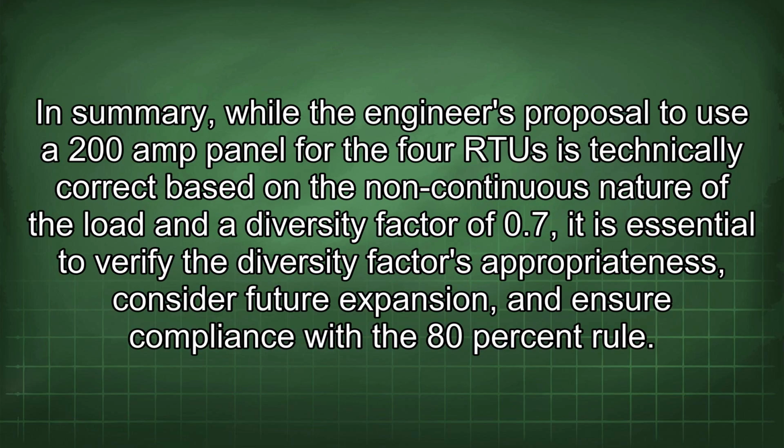In summary, while the engineer's proposal to use a 200-amp panel for the 4 RTU is technically correct based on the non-continuous nature of the load and a diversity factor of 0.7, it is essential to verify the diversity factor's appropriateness, consider future expansion, and ensure compliance with the 80% rule.